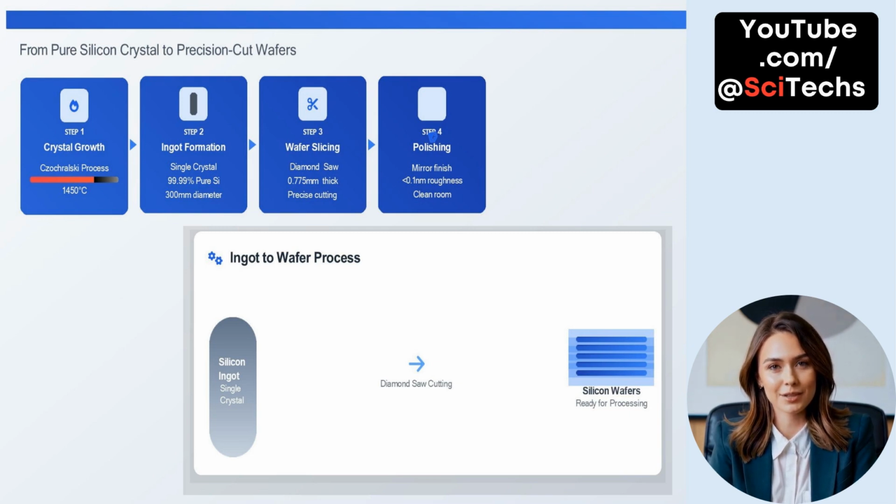Next, the ingot is carefully sliced into thin discs using a diamond saw, with each wafer measuring approximately 0.775 millimeters thick. Precision is essential to maintain uniformity across all wafers. After slicing, each wafer undergoes a meticulous polishing step. This creates a mirror-like surface with less than 0.1 nanometers of surface roughness. The entire polishing process takes place in ultra-clean environments to avoid contamination. The result is a stack of wafers, ready for semiconductor processing.